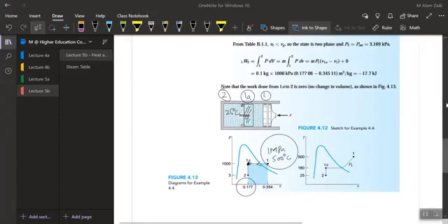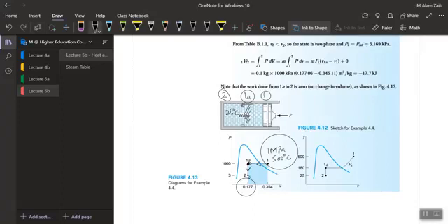As we know, we have got a volume now which is actually in a mixed region. So keeping the same volume constant and decreasing the temperature to 25 degrees centigrade, if you go down on a PV diagram, you can imagine that from state 1, which is 1A, we go down to state 2, which is again in a mixed region. So we would be looking at the saturated temperature table at 25 degrees centigrade, and at 25 degrees centigrade again we will be in a saturated region.